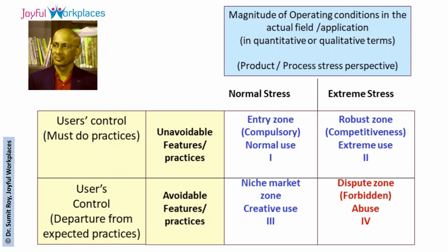For example, if in a particular place in India, we keep taking records of the operating voltage from time to time, the 95% of the operating voltage may be covered under normal stress, and the topmost 5% could be considered extreme stress. So for any designer, it is important to know, for every parameter of the product he has designed, what is the 95% common or normal stress level, and what would be the extreme stress